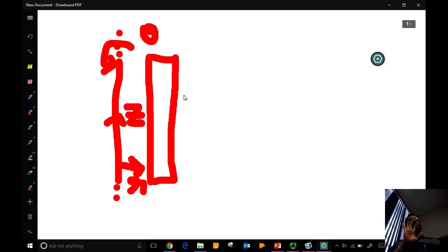From its equilibrium position, when there is no flow, it will tilt a little bit when the flow is there. The extent to which it tilts depends on the rotational speed. You put a bar on the top side to see how far the needle moves, and from the torsion in the rod that connects to it, you can measure the torque.